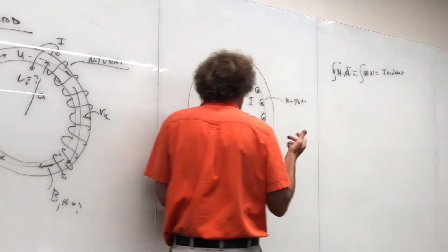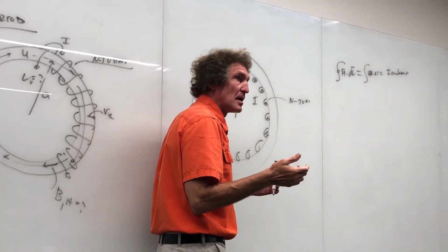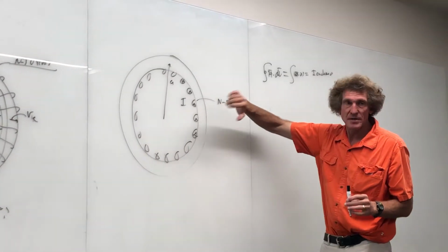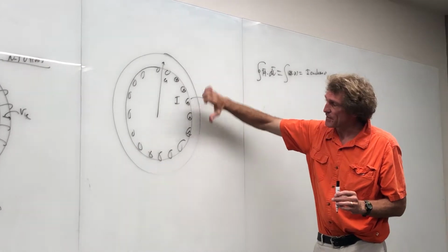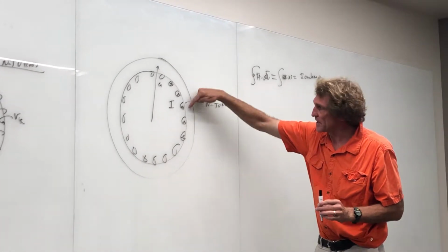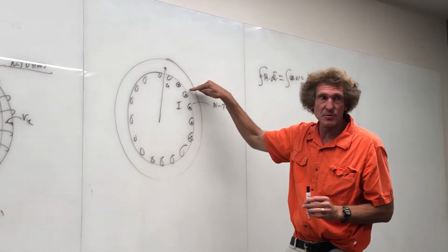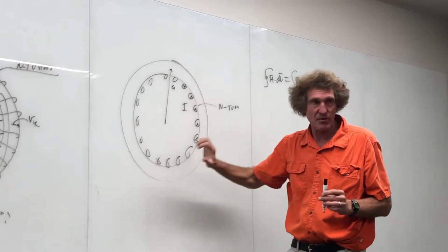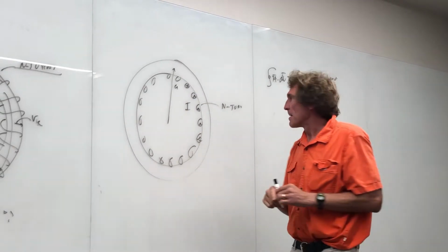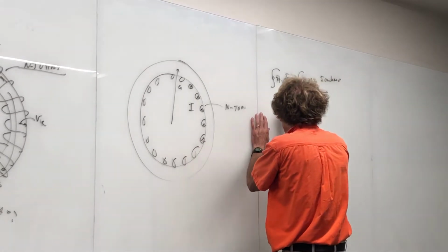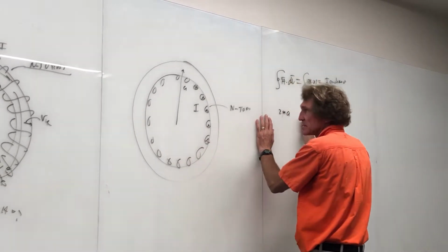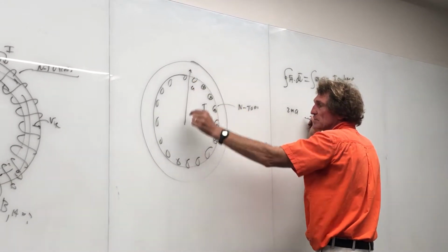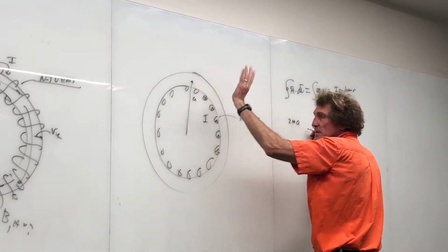Well, from the right-hand rule, and this is something we did last time, I know that if my fingers curl around in the direction of the current in these tightly wound turns, my thumb on my right hand points in the direction of the H field. The H field is going to be right around here. It's going to be azimuthal, right? It won't matter the direction, but it's going to be going this way if the current's going into the board. Do y'all see that? All right. So this is going to be 2 pi times A, since A is the mean radius. And I'm going to assume that A is so much greater than R C. The distance between here and here and here and here is insignificant.